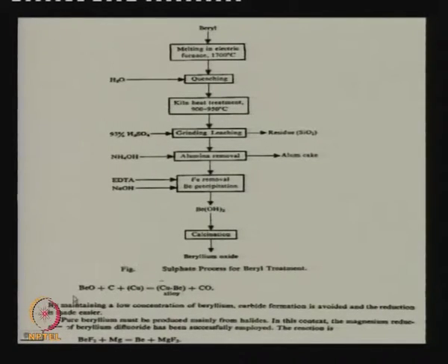Free energy change for the reaction is made more negative, reaction moves to the right. The beryllium activity being much low, beryllium carbide does not form, and copper beryllium that we produce finds application in industry readily. Here the beryllium percentage actually is very small, it is mostly copper.